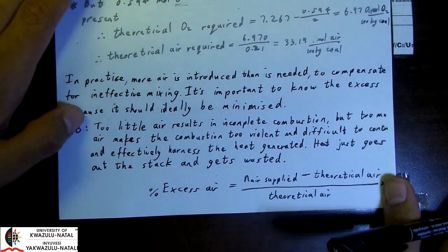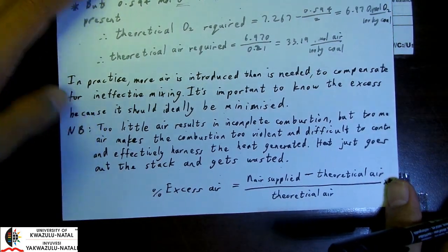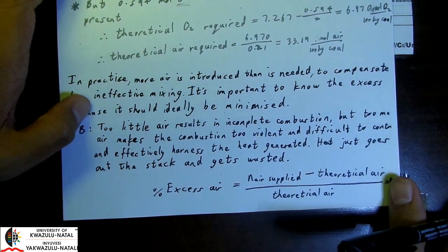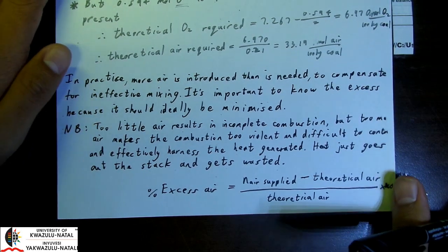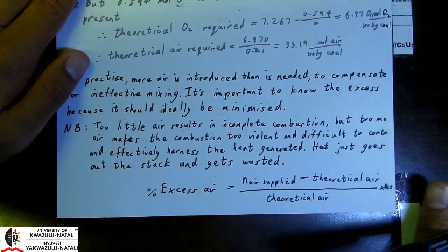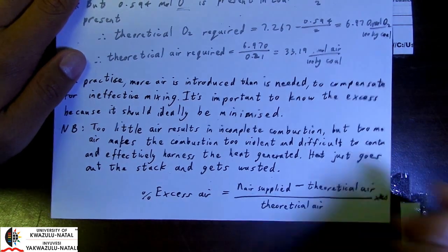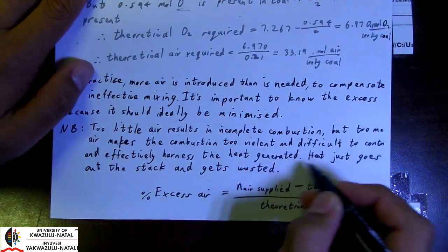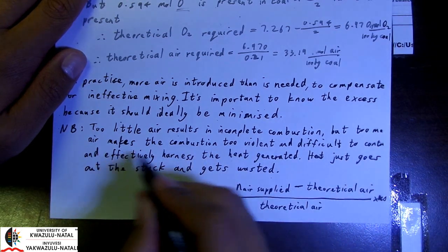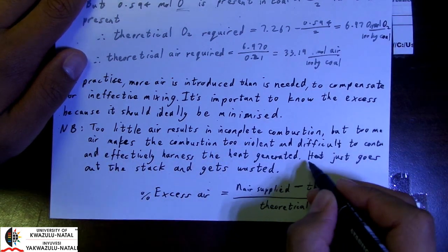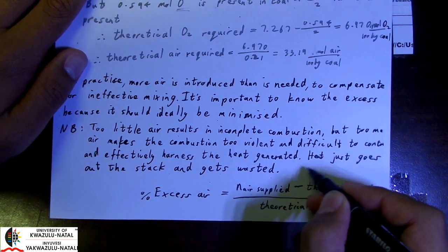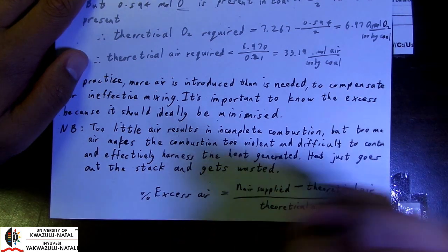However, if there's too much heat, then there's not enough water to actually capture that heat and turn it into steam in order to drive our turbines, so some of that heat ends up getting wasted. Okay, so if we have too much air and we have violent combustion, then our heat ends up getting lost through the stack and gets emitted.